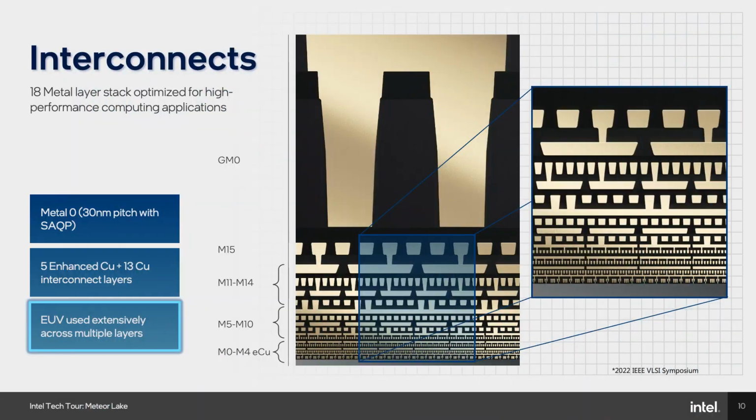The metal stack is 18 metal layers. Now we have a 0 metal layer, then we have metal 1 through 15, and then we have these giant metal distribution layers up the top. So it's 18 tall. You're also challenged by electromigration, right? Electromigration is when you're putting voltage or power on a wire. Sometimes that metal wants to move. And metal moving is not a good thing. Right? No.